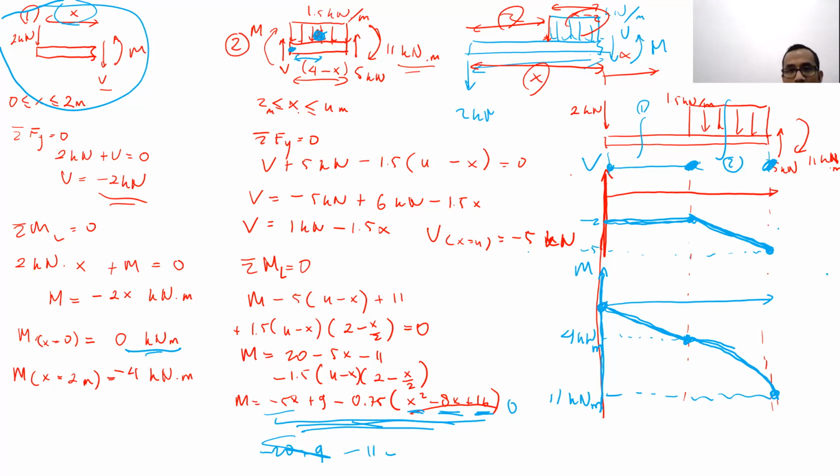The internal force and internal moment at a certain location, so only at one point, right? Yes, sir. In that case, just do the section at that particular point, and after you draw the free body diagram of the section, you can replace the distributed force with the concentrated force, but always replace the distributed force with a concentrated force after you draw the final free body diagram. Do you get it? Yes, sir, I get it.